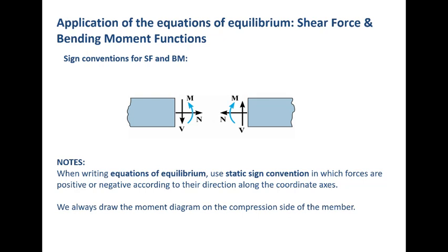What we're interested in structural analysis, that's the main thing, is calculating the internal actions, namely shear force, bending moment, axial force, or internal torques in some cases, torsion. So we're interested in those internal actions that we do not see.